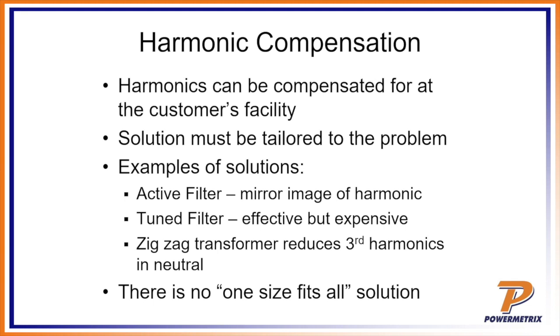What that means is that you really have to go out and do a power quality study at the customer site to understand, A, what is causing the harmonic, B, what frequency range you are talking about, and then C, how do I tailor a solution basically to fix that. A couple examples of solutions. Most of the time it's going to be a filter of some sort.